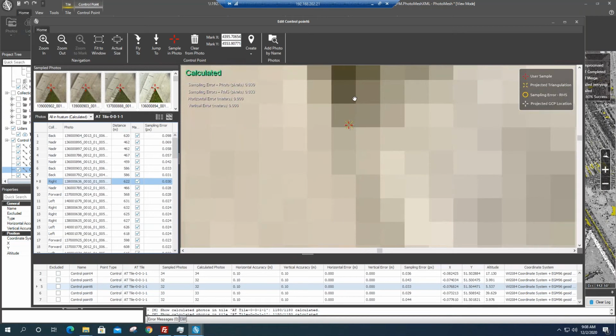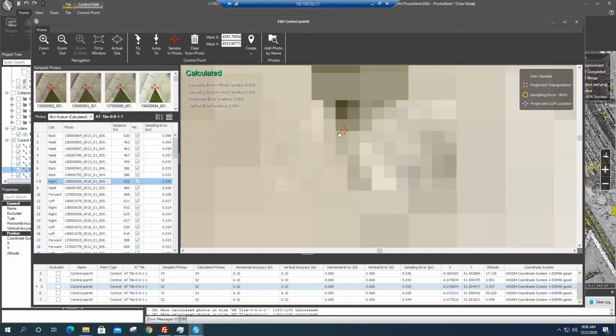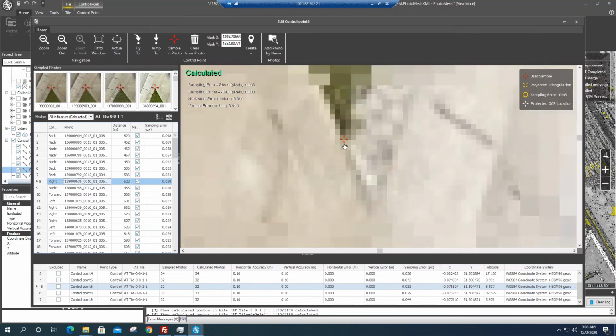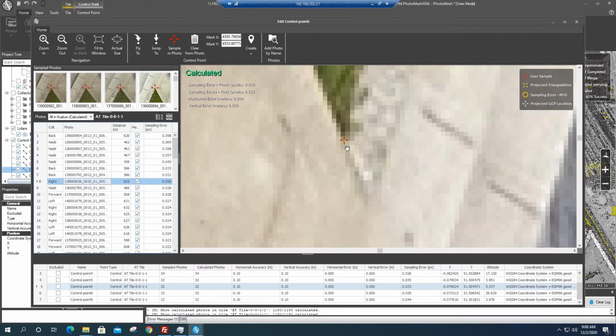They're asking, is there tight integration of image and LiDAR georeferencing, common bundle, including image and LiDAR strip adjustment? So we don't do the strip adjustment for the LiDAR. We work with different partners that work on the LiDAR processing side. The LiDAR usually is processed for its highest accuracy before it's integrated into PhotoMesh, but we have the ability to then match up and cross-optimize the image-based point cloud and the LiDAR-based point cloud.